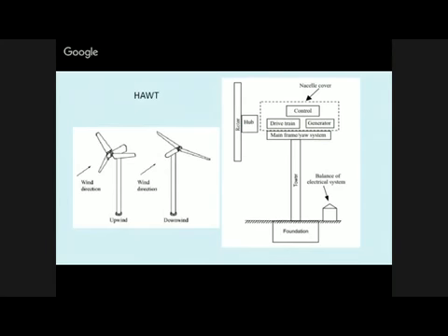The main components in horizontal axis wind turbines are the rotor, hub, then the nacelle cover, which includes the control systems. Drive trains are required. The reason is that the movement of the blades is quite slow, and for the generator, speed is required. In that case, a gear mechanism is used to increase the speed. The rest are the main frame or yaw system, in which the direction of movement of the horizontal axis is given, and others are electrical components.